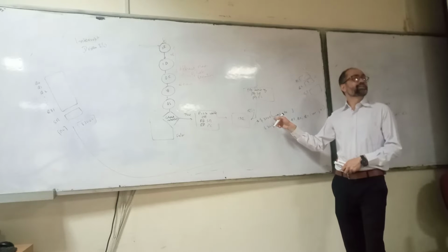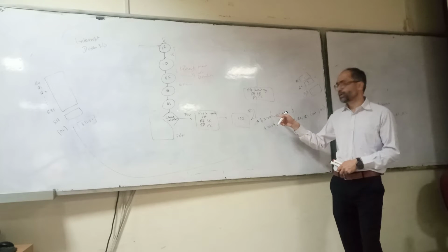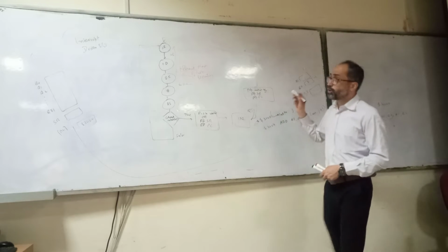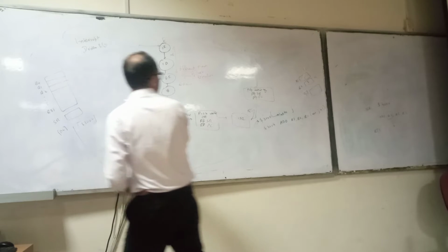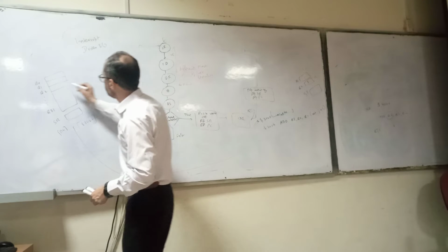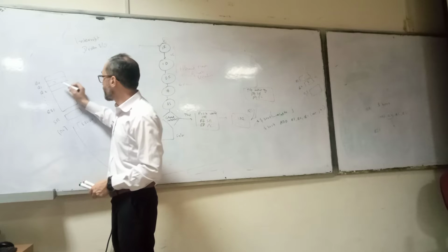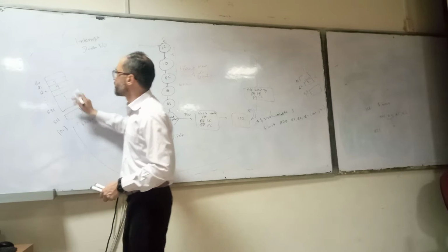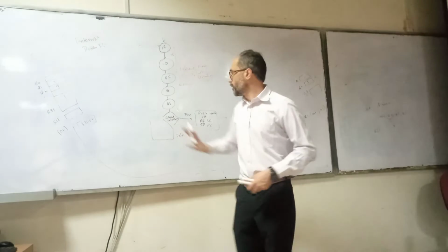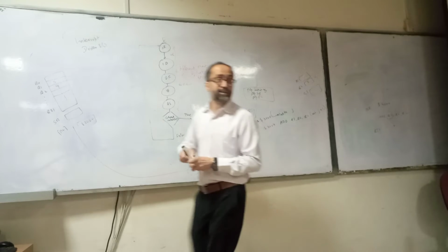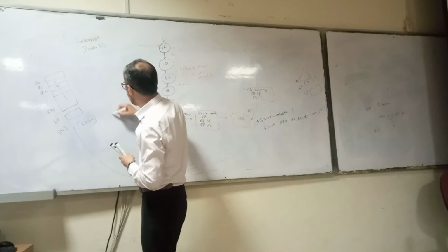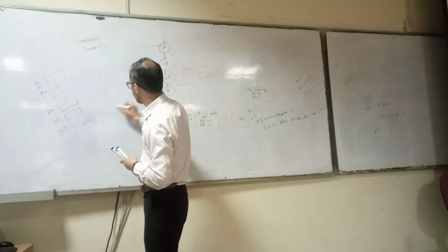During the middle of this instruction, the microprocessor will execute this instruction. It will store, okay, now what is the contents of R0? In this example, what is the contents of R1? 5. What is the contents of R2? 9. And I'm not interested in any other contents. So before jumping to the ISR, these values will be pushed on the stack. So what will be the stack values? The stack values will be like this.